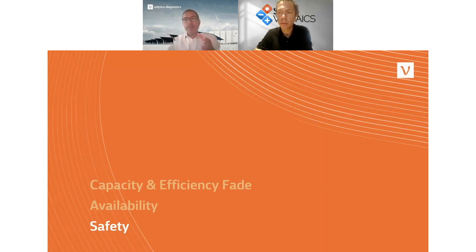So what that does is it avoids inhomogeneous degradation. We just learned that next to this SOC window in which you operate and the charge rate or power with which you charge and discharge, the temperature is definitely very much affecting the degradation. Now, if you have in a module with several dozen cells an inhomogeneous temperature distribution, this leads to inhomogeneous degradation.